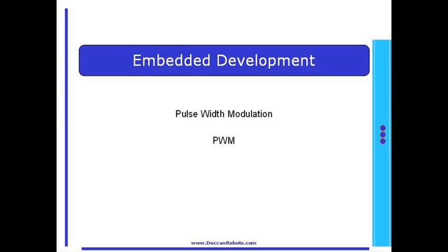PWM is another interesting topic for AVR. You can use PWM to generate various frequencies. These frequencies can be used to control intensity of a LED, control speed of DC motor, generate interesting sounds, etc. Let's understand how to generate a PWM.